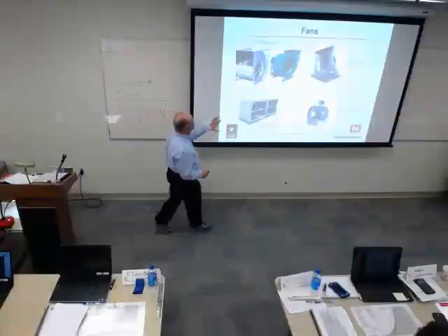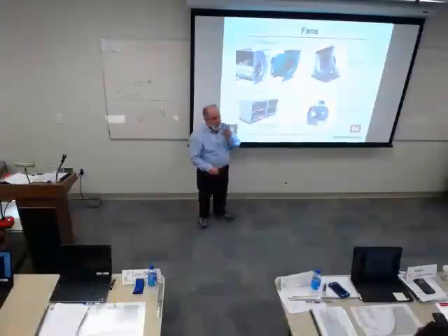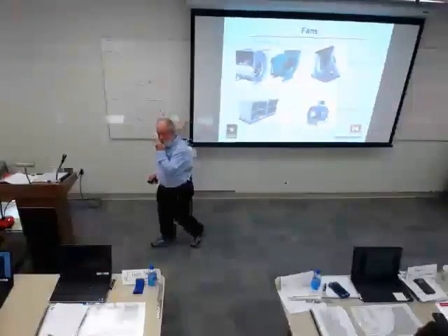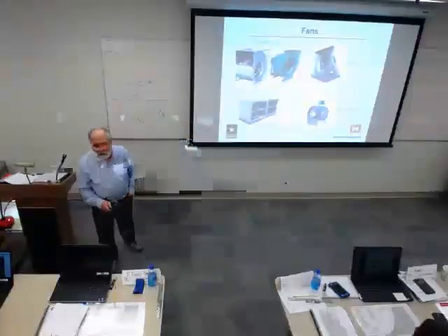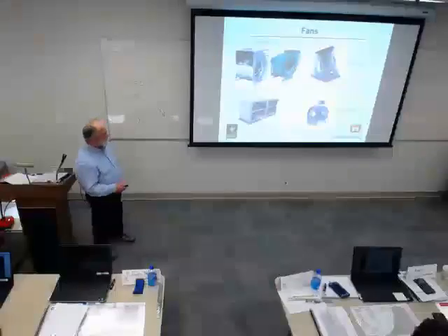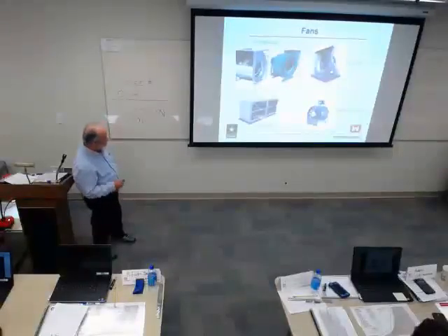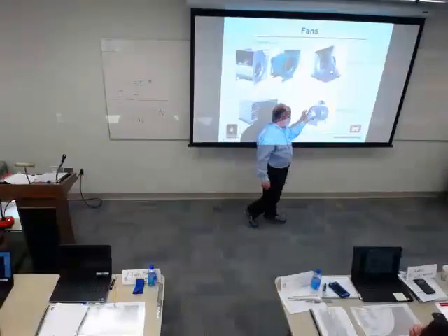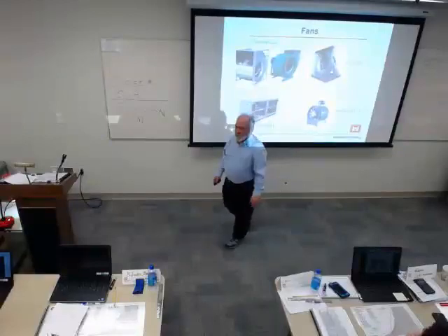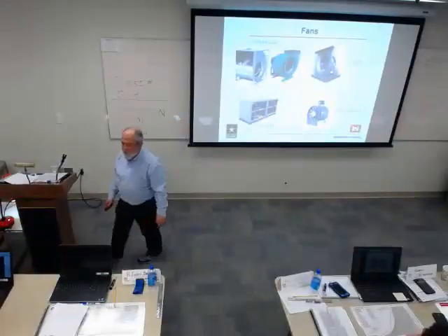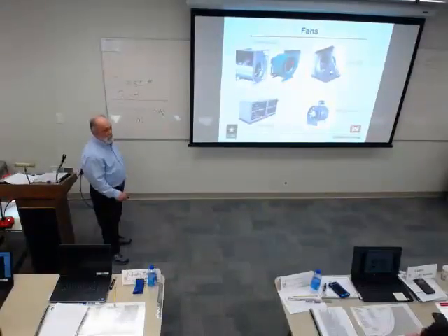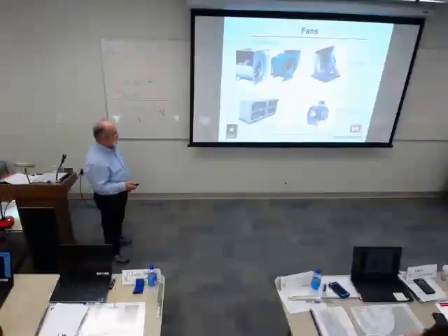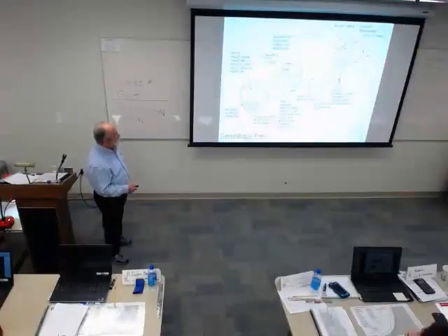Here's what we call a fan wall. And we're seeing more of that. There are a lot of pluses and minuses in those too. And currently I'm seeing a lot more minuses than anybody had anticipated. But that's not a part of TAB, just that there are pluses and minuses for all fan types. Vane axial is this one right here, which is very similar to one called the tube axial. All I want to say is tube axials and vane axials look a lot the same, but there are some minor differences that differentiate them.